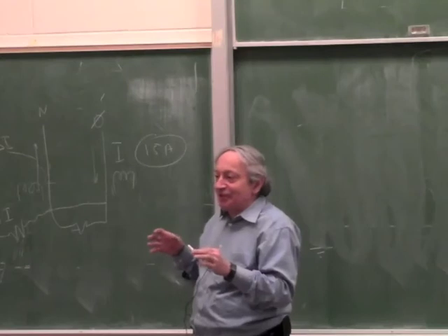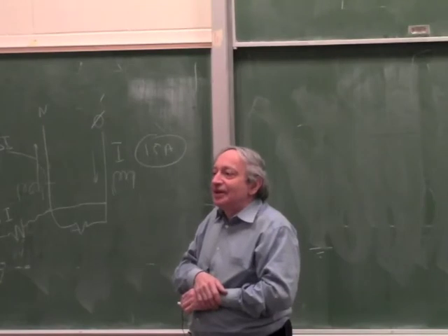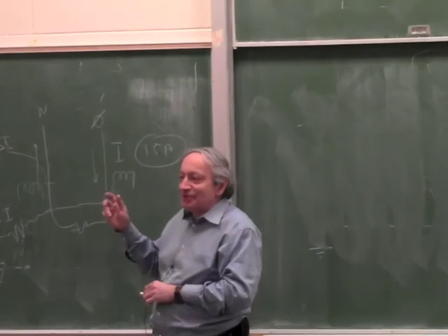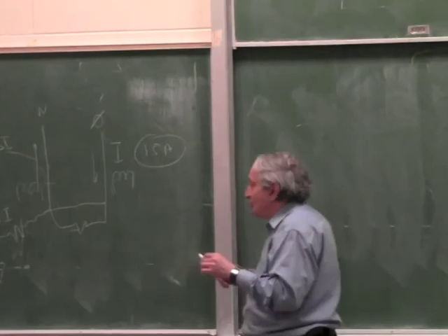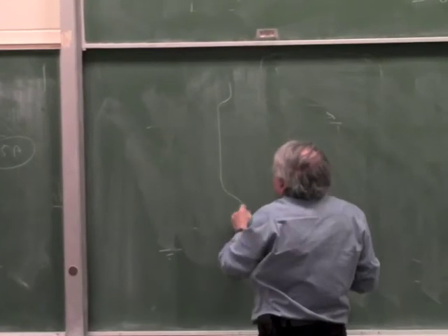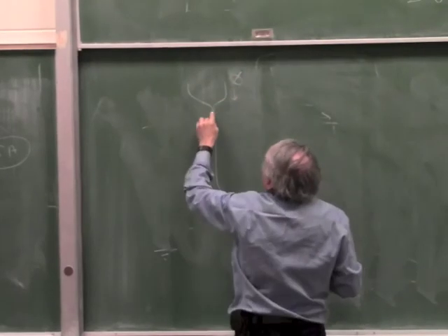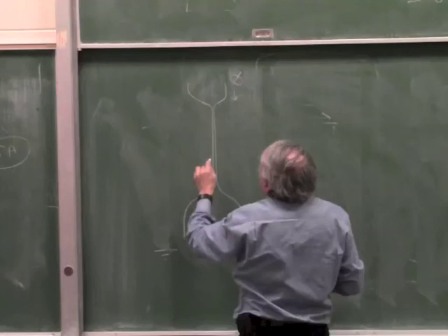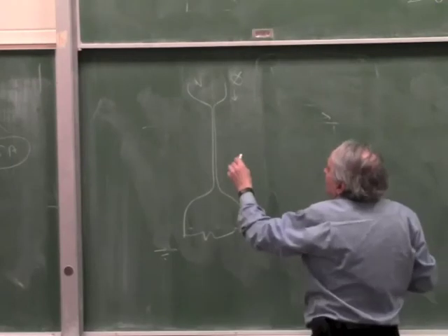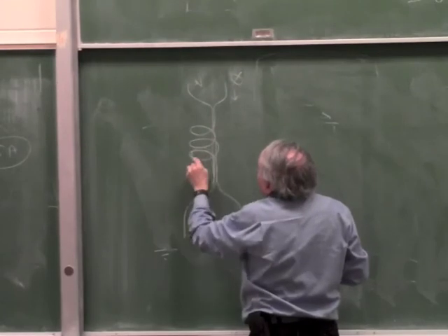There is a simpler way actually. But the simplest way is yes. Not so simple, because you really want to measure currents here, so it's not so simple to set up a Wheatstone bridge. But I think the way it's done, which is a bit simpler, what you do is you take the current which comes in, this is the phase, and you put it together with the wire which comes back, this is neutral. So you have a double wire, and now you take this double wire and you wind it as a coil, maybe just like 5 or 10 turns.